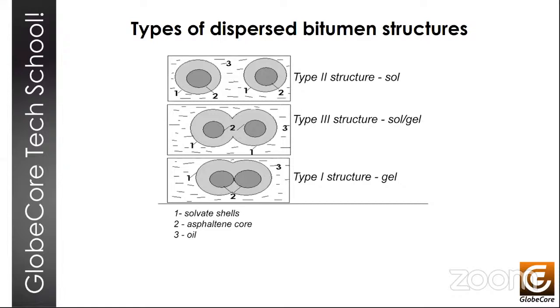Type 2 bitumen has a few advantages, such as high cohesion and deformation resistance in an elastic viscous state. It has increased resistance against oxidation that causes aging. The disadvantages, however, are lack of elastic and elastic plastic states, low heat resistance, and poor water resistance. So residual bitumen mainly belongs to this type 2.